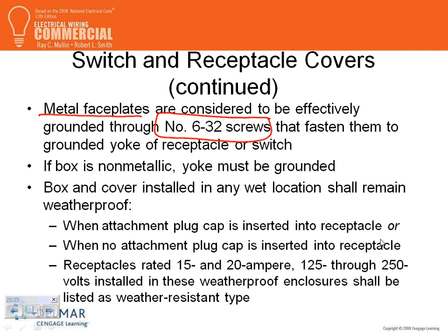Okay. Wet location, guys. In 2008 and 2011, if you have receptacles or plugs in a wet location, the receptacle in a commercial building has to have a cover that covers the plug while the plug is engaged in the receptacle. In 2011, they made it even worse.